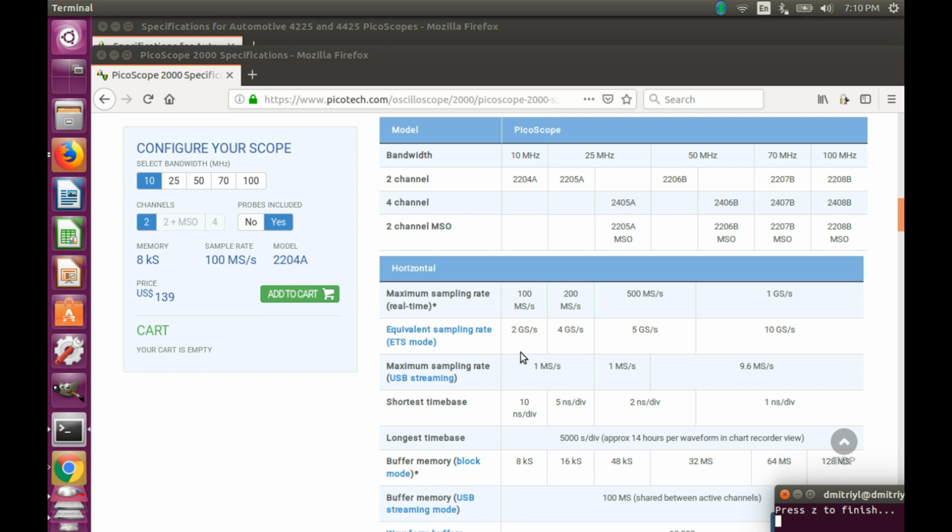This is not enough to have a detailed view of the waveform and not enough to do the serial decoding. However, you will still see the transitions, and you will be able to confirm the maximum and the minimum voltages on each line, see that the signals mirror each other, and so that might be enough for your diagnosis.